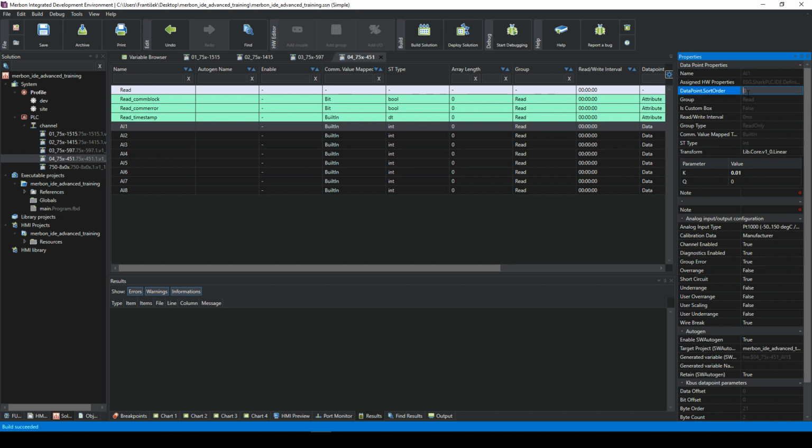So it may be a little bit of a disadvantage for you because you can't choose the type of each input or output. But the advantage of the card system is that you don't have to buy a big PLC if you want just, for example, 40 IOs. You don't have to buy a whole MX, for example, and there is no such big space needed.